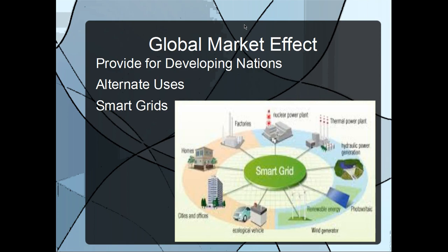While there are numerous benefits to industrialized nations using SMR technology, developing nations stand to see the most gains. Many developing nations lack the financial resources or robust electric grid to build traditional full-scale gigawatt-sized nuclear power plants. In order to ensure grid stability, the general rule of thumb is that the unit size of a power plant should not exceed 10% of the overall electricity system capacity. Using this rule of thumb, an electric grid would need to have roughly 12,000 megawatts of generation capacity in order to fully accommodate a typical full-scale 1,200 megawatt nuclear power plant. This is beyond the capability of many electric grids in non-connected rural areas or developing nations.